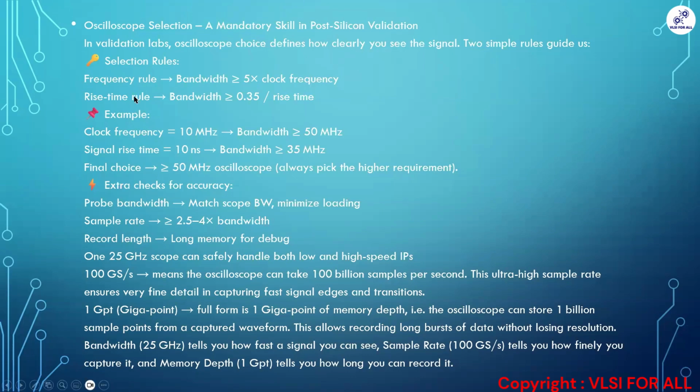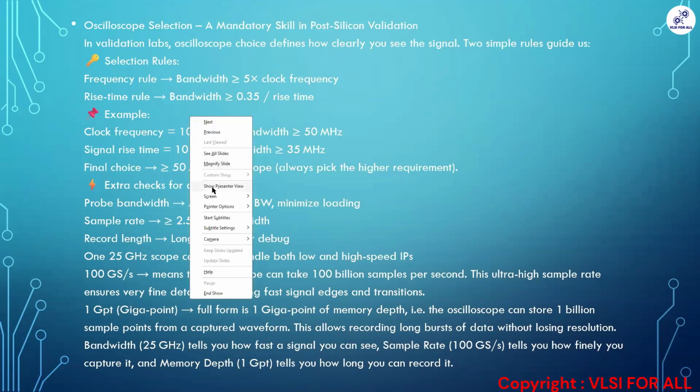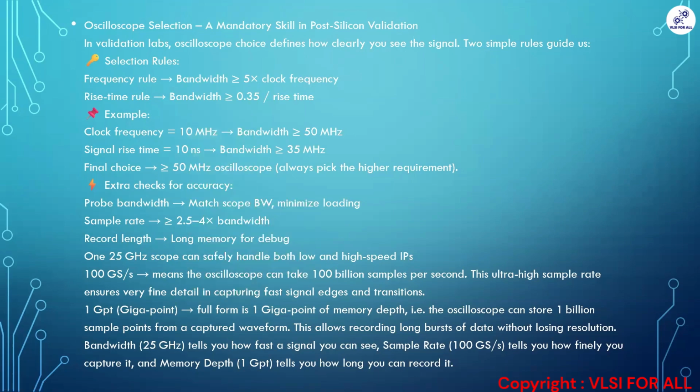And the rise time rule will be 0.35 divided by rise time. So that is the rise time rule.